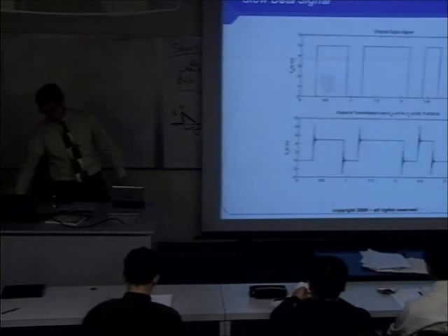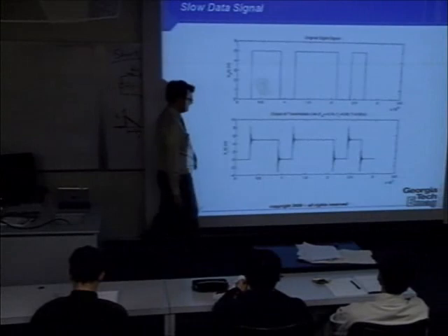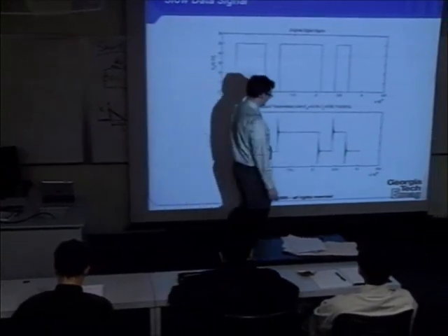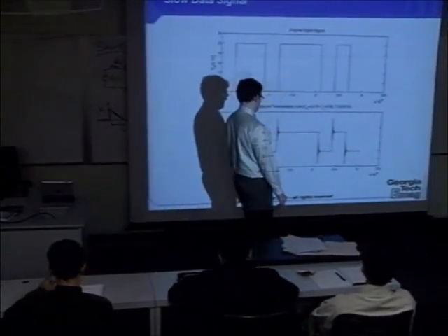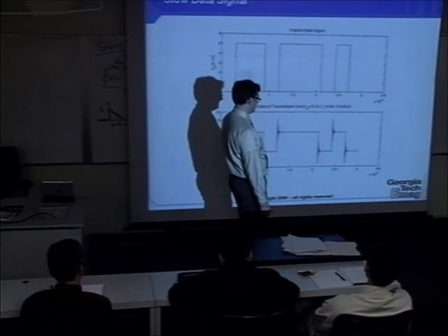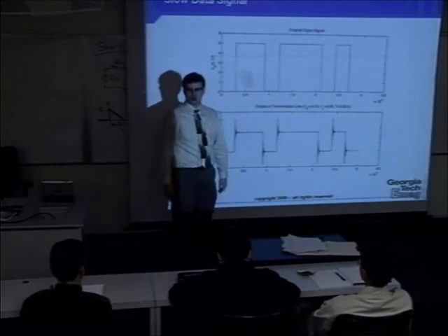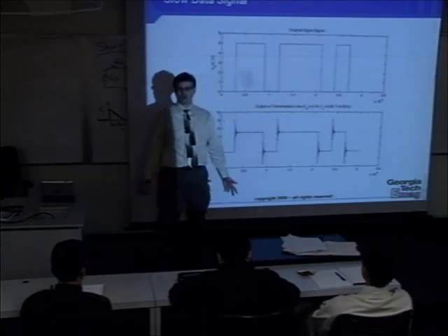So let's take a look. First, I'm going to use a wide pulse. Here, my bit period is something like, I don't know, looks to be about 0.25 times 2.5 times 10 to the 6th, so about 2.5 microseconds. That would correspond to a bit rate of like 400 kilobits per second.